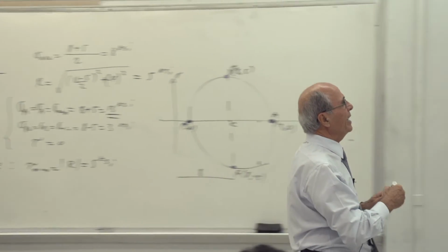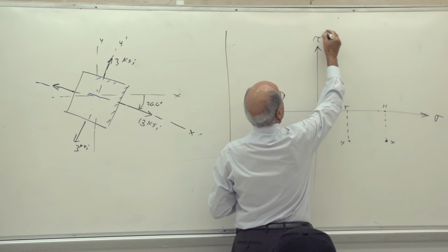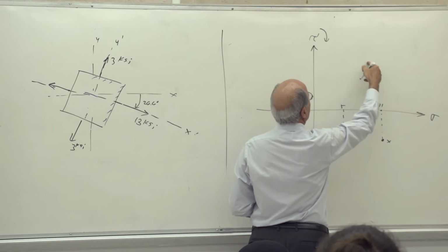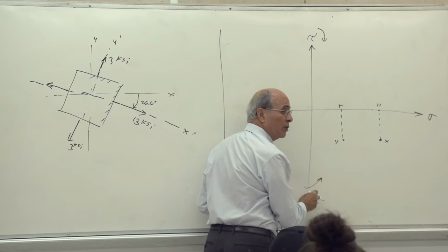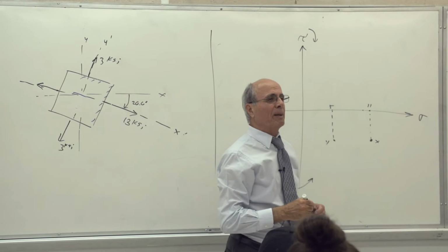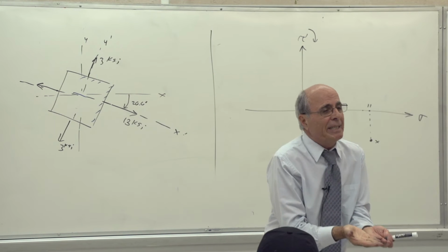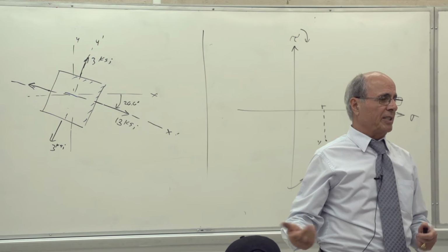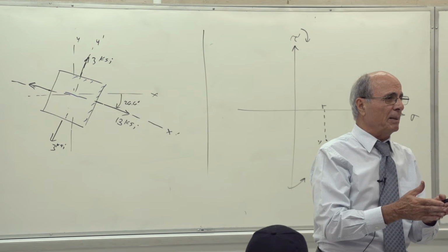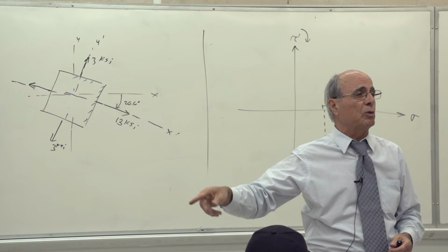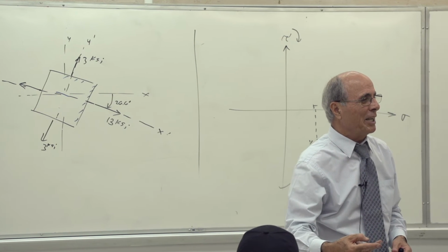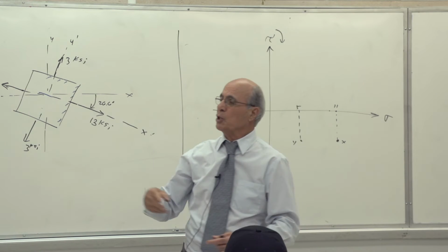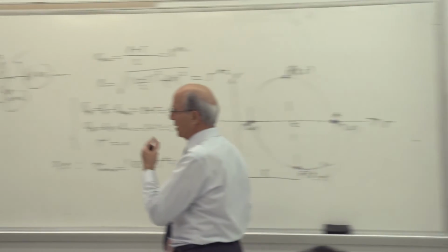If you look in the book, you see there is a little arrow there. Any shear stress going this way, he puts it up. Any shear stress going that way, he puts it on the bottom, in order that 180 degrees becomes 360 degrees. Remember the joke I said? That was not really the case, but that's why he had to change all his equations from theta to 2 theta. So all the angles here become twice as much. That's another thing. So let's go one by one, not mix all of them together.